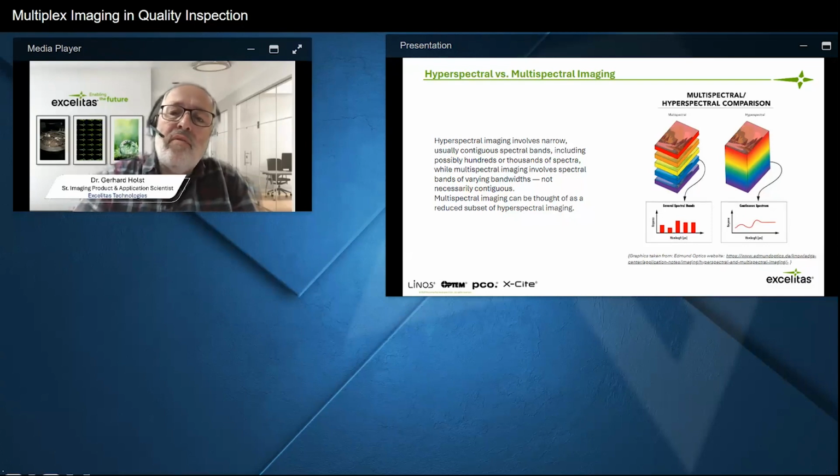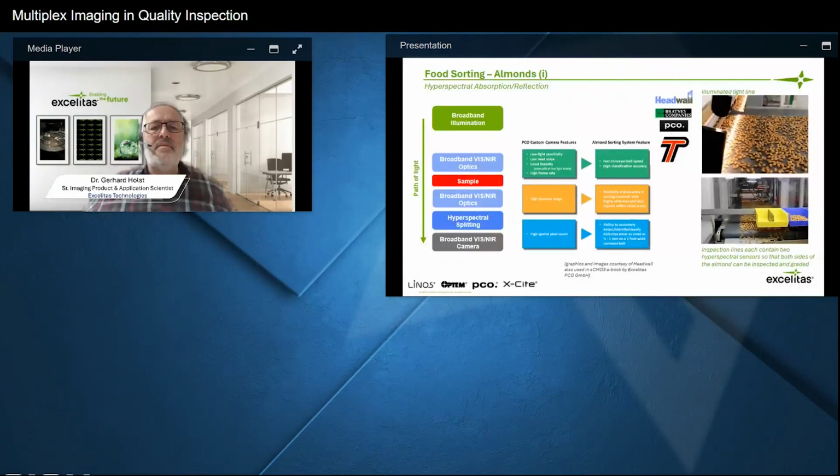If you are going more for hyperspectral imaging to collect more information, then in most cases, if an array type of image sensor is used, the image sensor is turned into a hyperspectrally resolved line scan sensor. So in one direction, you get the spatial information, while in the perpendicular direction on your image sensor, you get the spectrum. And for these types of investigations, you either have to move the camera or the sample to get the hyperspectral information for the whole image. But let's come to some examples.